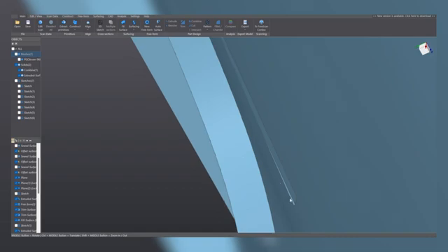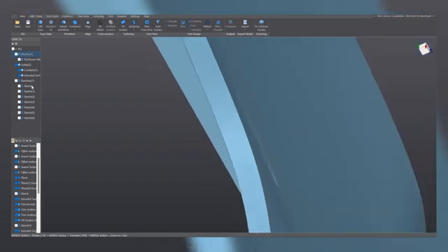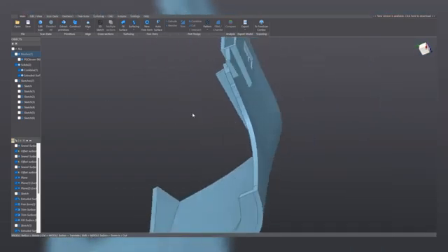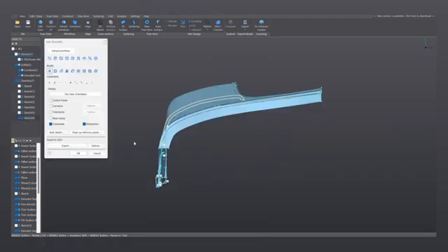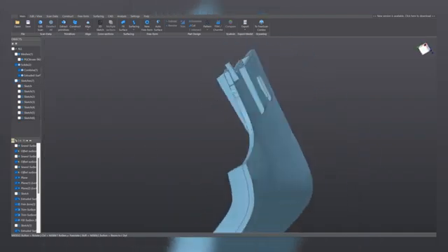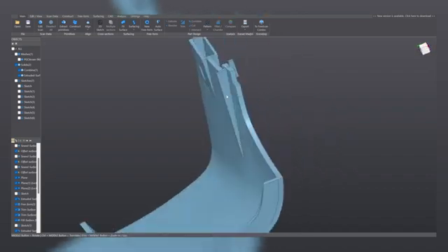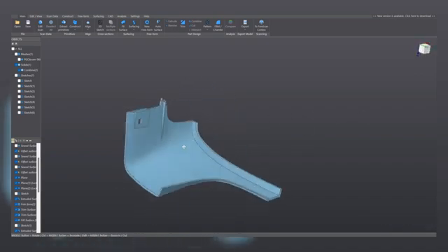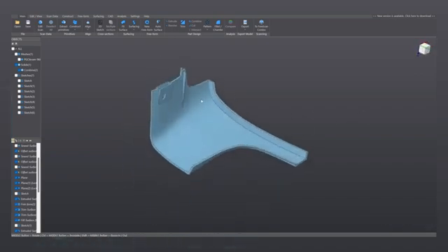It's too large and it goes beyond the original body. So let's correct this. We double click on the sketch and we edit a little bit this line here, and now it's inside the body. So now we can choose both solids, combine them together, and that would be how we reproduce these prismatic shapes.